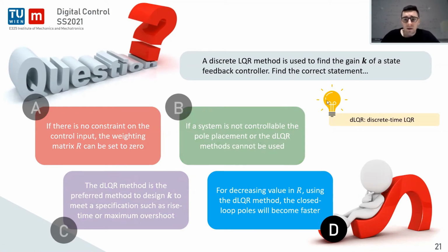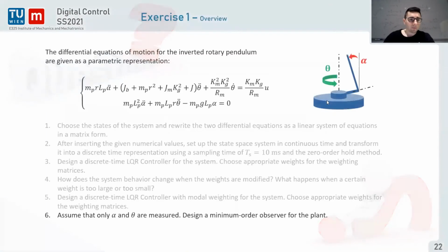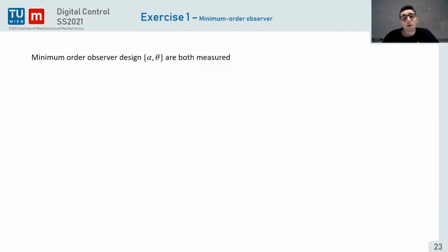So now let's move to the last part for today. The last part is about control observers. Last session, we designed 2 observers, the current and the predictive observer, using only one measurement, the output measurement. Today, we're going to say that we're lucky enough to have 2 measurements available, which are alpha and theta. Each of these measurements directly corresponds to a state, so we're measuring 2 states.